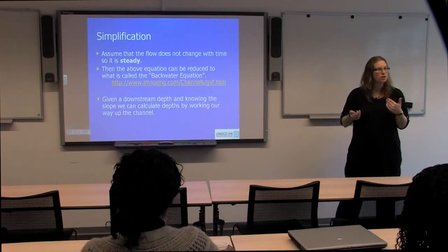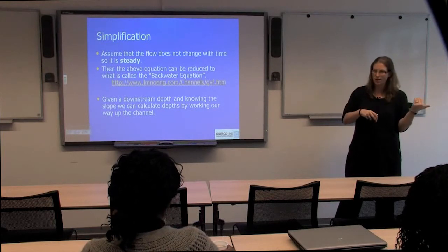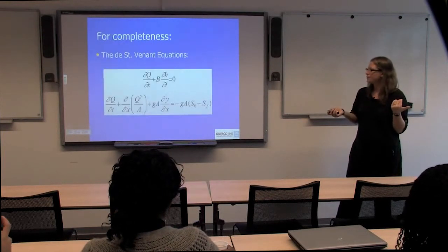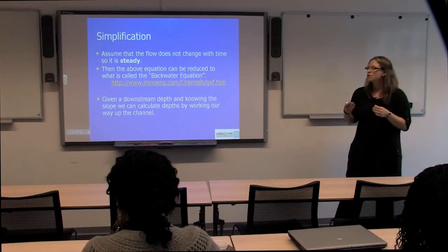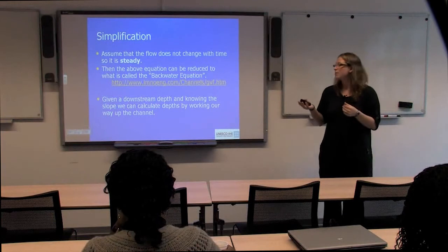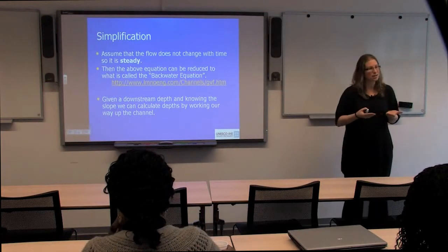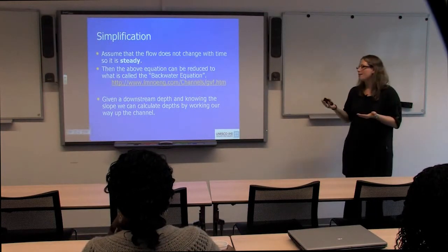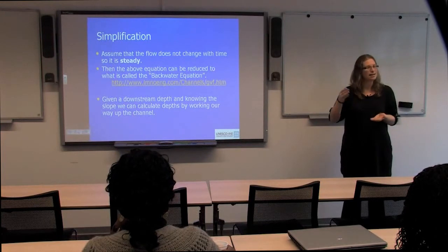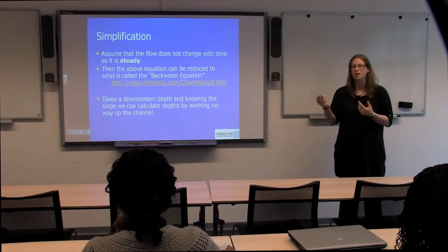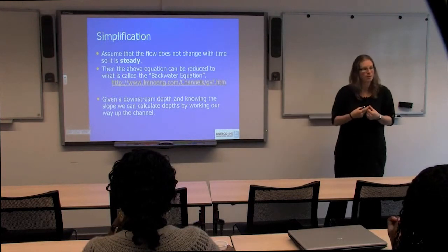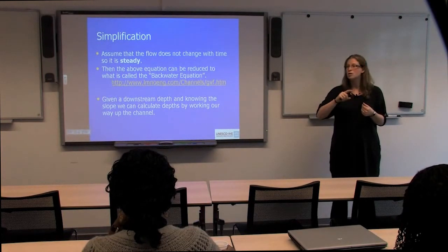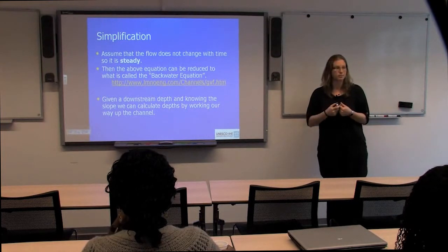And then we can reduce the previous equations to the backwater equation, which, given a downstream depth and knowing the bed slope, we can then calculate depths along that slope. So you may remember from your hydraulics the backwater equation.